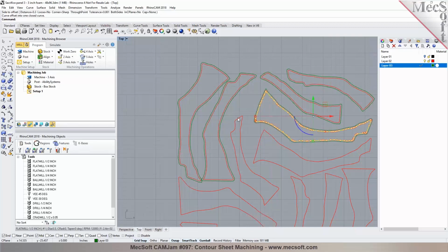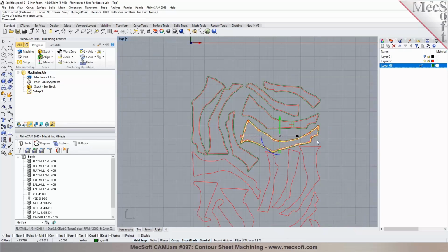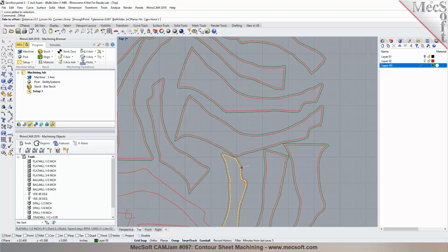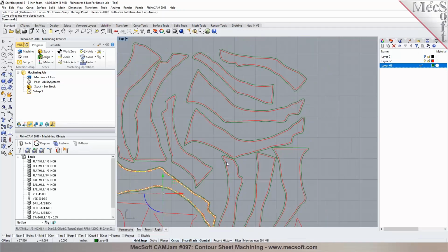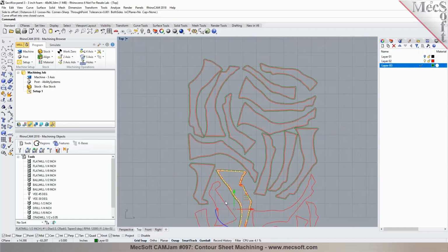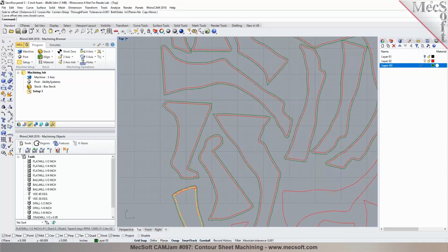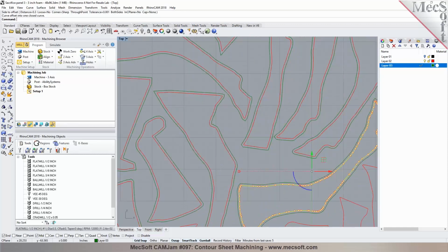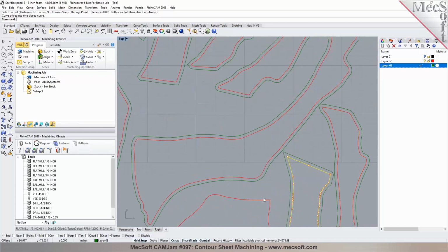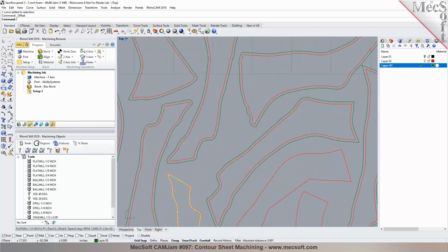You can even script it in Rhino to go ahead and run this command repeatedly multiple times, so you don't have to manually do it for each and every part in here, right? So all I'm doing is selecting it, pressing enter to repeat the previous command, and I'm able to quickly offset these boundaries in here. So this gives me a nice area around the part, so I can get all the way down on the sides to be able to machine the part to the floor. So I'm just defining a boundary in here and offsetting the boundary by 300 thousandths as you see it right there. Would you have any questions so far?